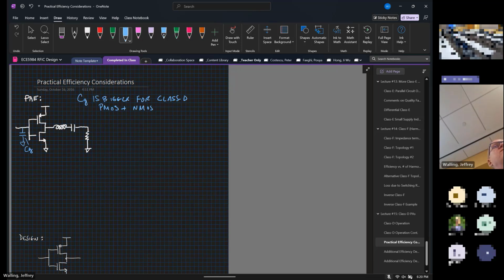Say this is the Class O amplifier. Yeah, I would not say this is a Class O, but it was named Class D well before Class O, so maybe that's why they didn't try. So there's power consumption whenever we're switching that gate. This is 1/2 C V_DD squared f. I also have a parasitic drain capacitance.